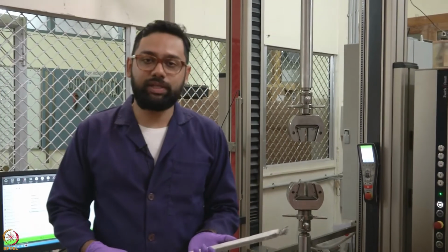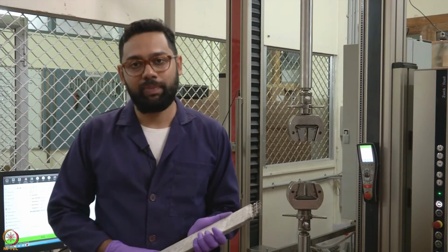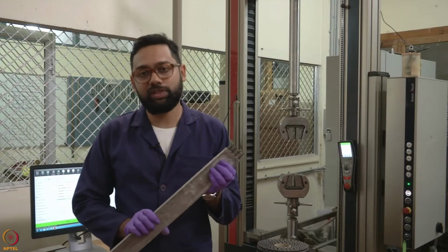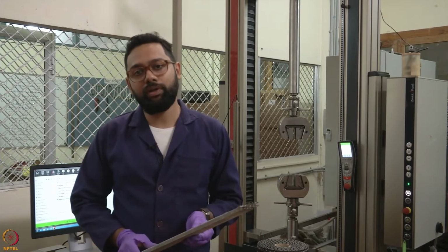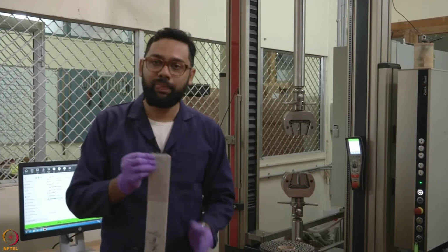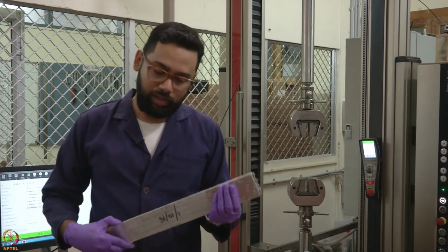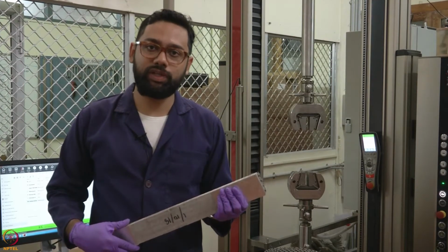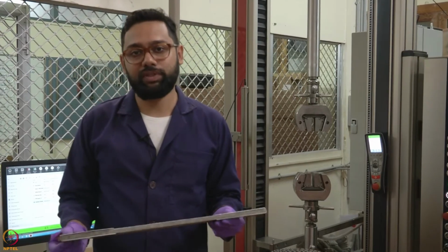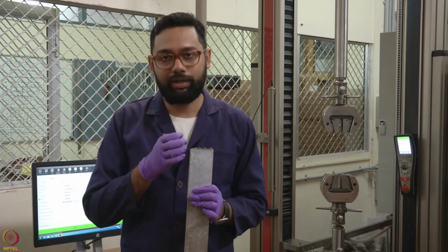The problem with the uni-axial tension test is that gripping is the primary problem, how to grip the specimens. So we use aluminum plates attached to the ends such that crushing failure does not happen during the gripping process. These are specimens attached with the aluminum plates. We cut out rectangular aluminum plates for the gripping area and fix them with epoxy resins and let them cure for 1 day. Then we do the test after that. This prevents crushing failure of the support due to the pressure that builds up during the gripping process.